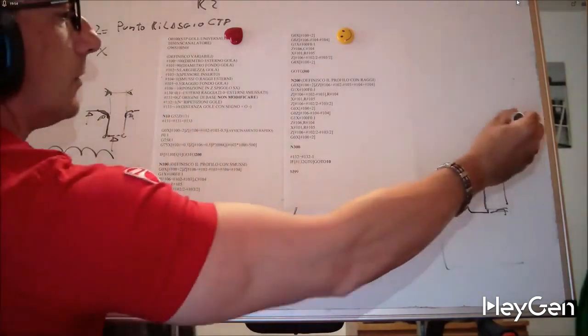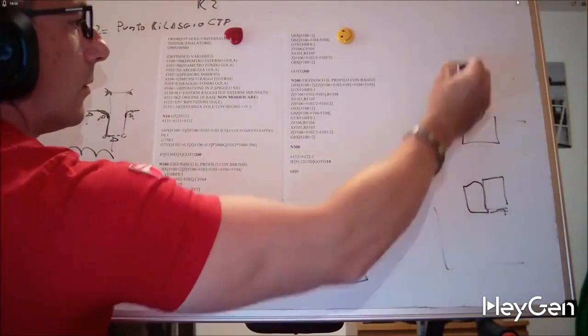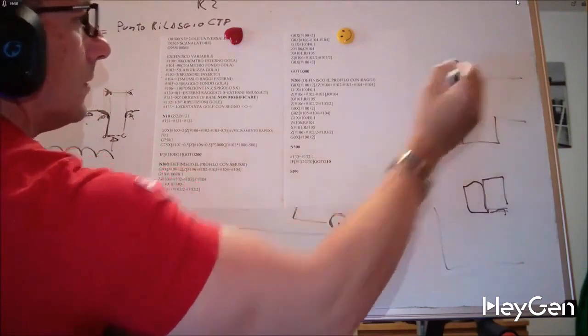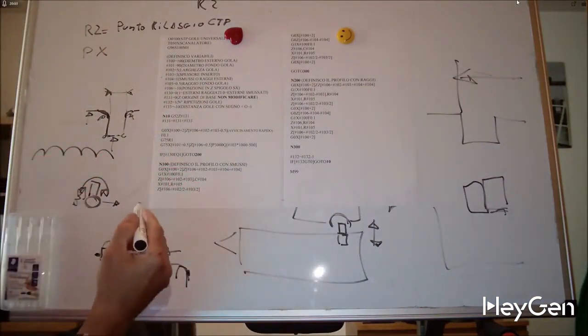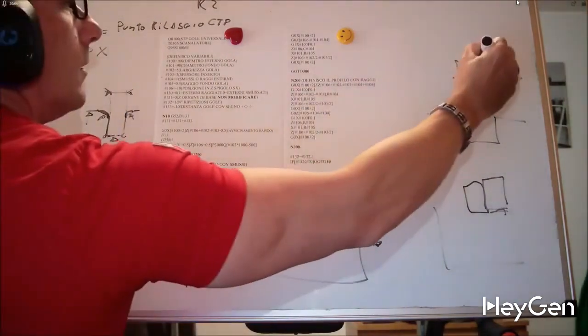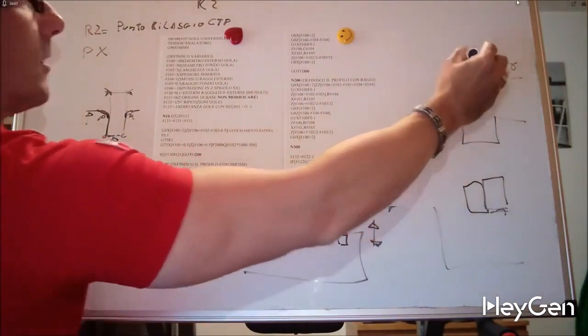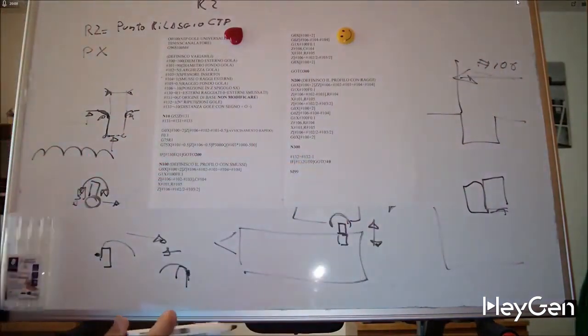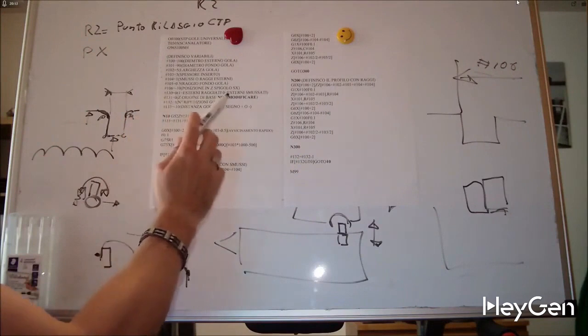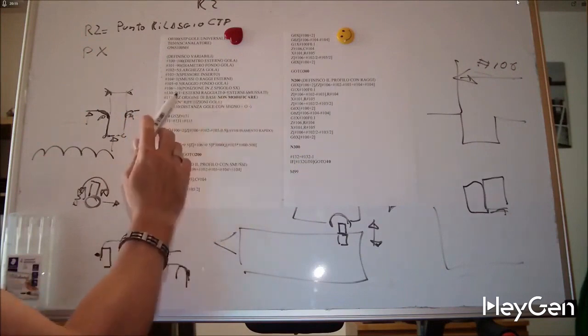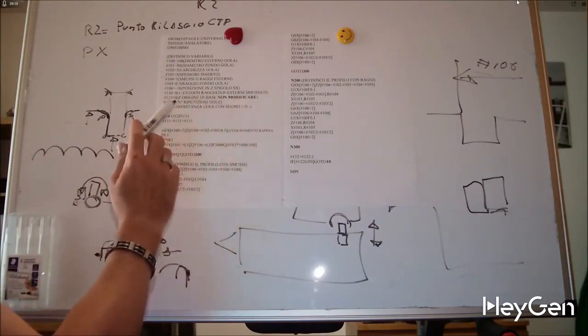You see, these are all variables. The Z position of the left edge, this Z. I need to know where my groove is located. So this is percentage. And I always say percentage hashtag 106, 130. I have 0 for the chamfered outsides, and I put 1 for the radiused outsides. 0 is not to be changed.